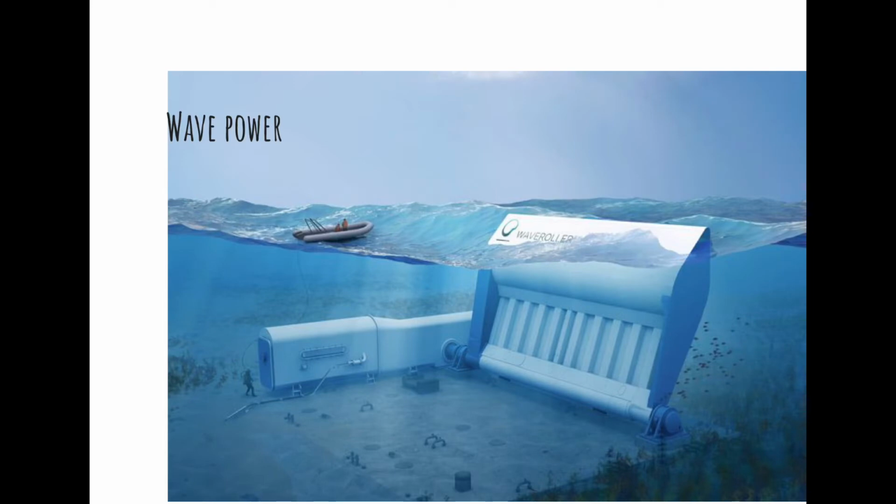You can also do wave power. This is a type of wave roller technology, and that produces the same as the tidal power one, so about 1 megawatt. But you can have lots of these in the ocean going back and forth all the time. So it's like a farm of them, similar to wind turbine farms. You can have wave power farms. They're pretty hard to run though. Seawater, salt water, is really hard on mechanical components. So that's why these technologies have been a little bit slower to develop.